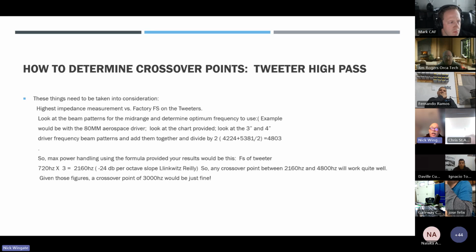This is called beaming. And what beaming is when you have a speaker that starts to approach a certain frequency. And because of the shape of the cone and the way that the speaker is designed, it stops being omnidirectional, or it starts to where the frequencies start to narrow, and they fire straight at you or straight across the car.